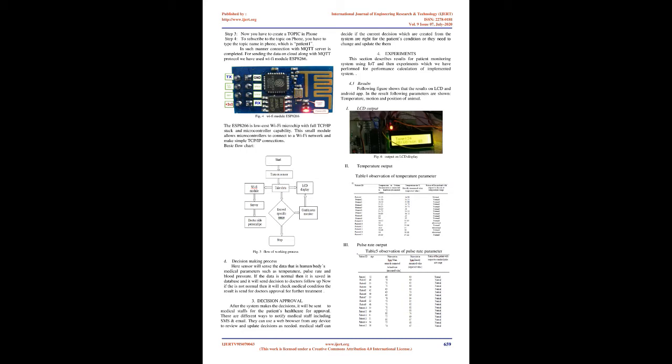The sensors transmit real-time data to the cloud continuously based on the set conditions which are in their configuration program. The DS18B20 digital thermometer gives 9-bit to 12-bit Celsius temperature measurements. The DS18B20 communicates over a one-wire bus, requires only one data line and ground for communication with a central microprocessor. In addition, the DS18B20 can take power directly from the data line. It does not require an external power supply.